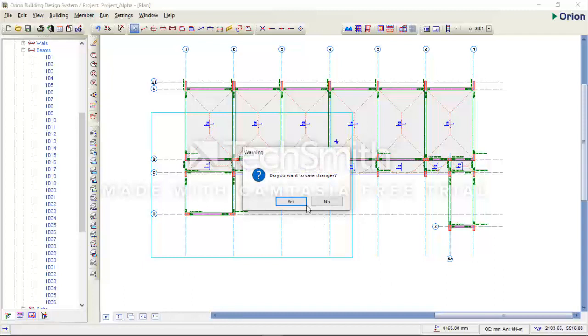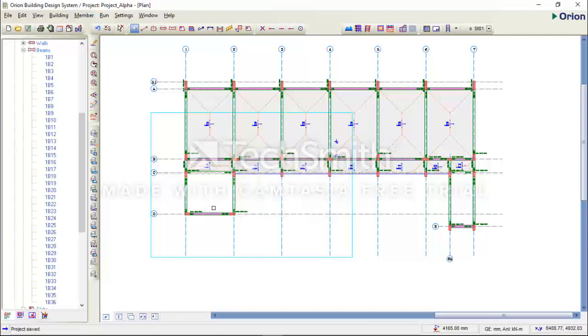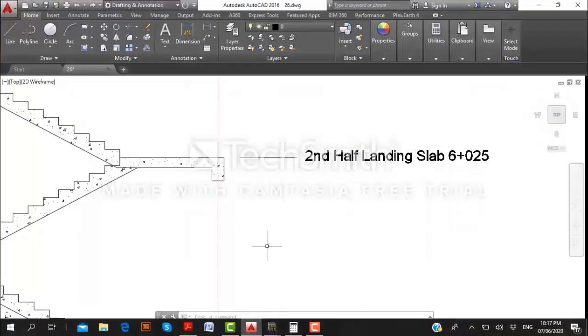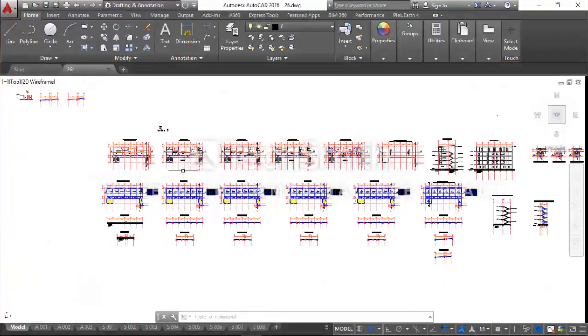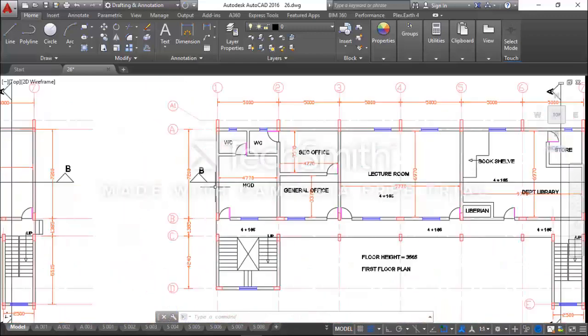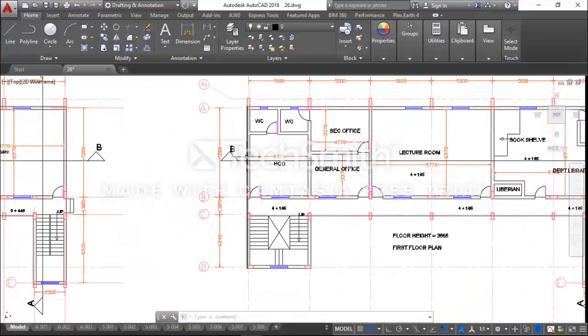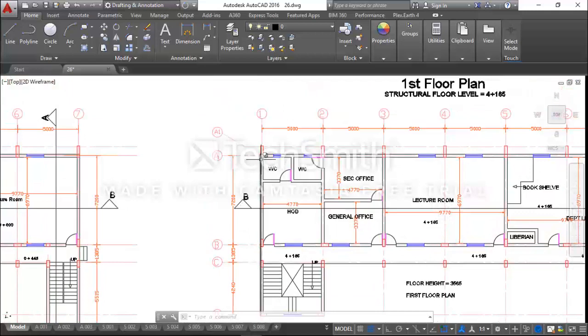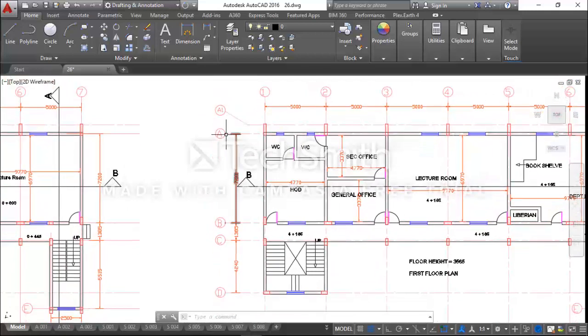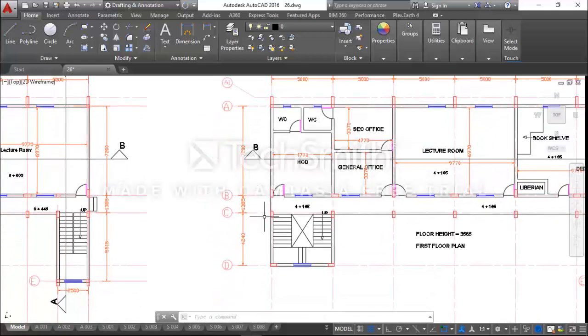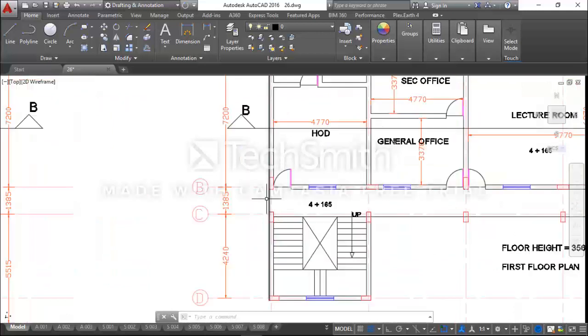So I specified the load along the horizontal grid. Now let me check the beams along my vertical structural grid on my architectural drawing. On my first floor plan, for the line 1, we have wall load between the line A and B, and also between the line C and D. Between B and C, we don't have a wall load there, but there will be a barrier here.